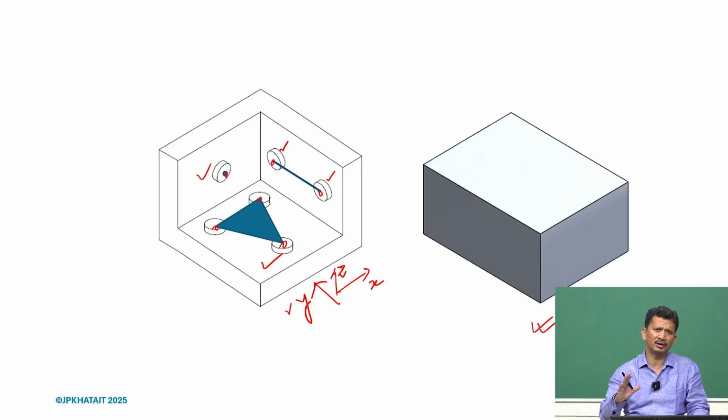So of course, we need some way to make these contacts possible. What we later refer to is the nesting force. Some kind of nesting forces will be required, or we can use bolts and whatever is required to maintain those contacts. What we realize here is the location of this object with respect to the wall is defined.